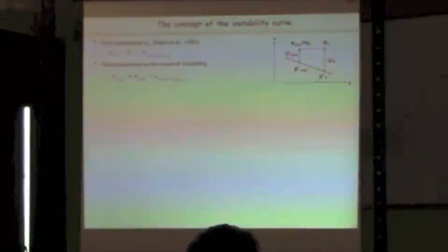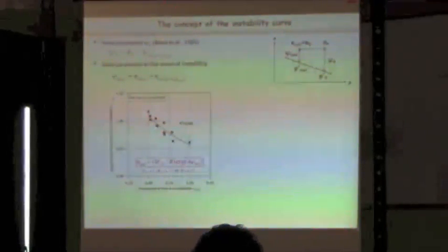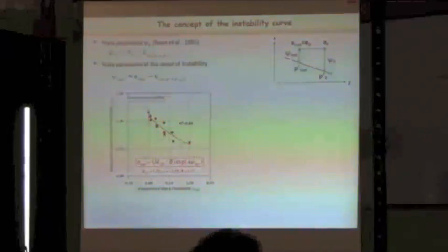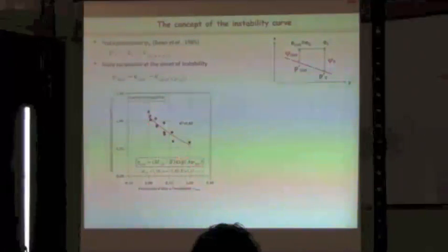This concept is based on the state parameter psi0 introduced by Been. So for our case, we replace this psi0 by psi instability, and we calculate it by using the void ratio at the instability minus the void ratio at critical state corresponding to P dash equal to P dash instability. Then when we plot our eta instability versus the psi instability, we see that all our data merge on the same curve.